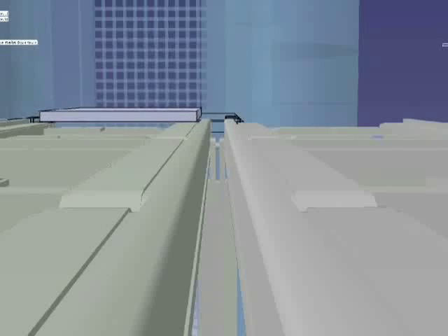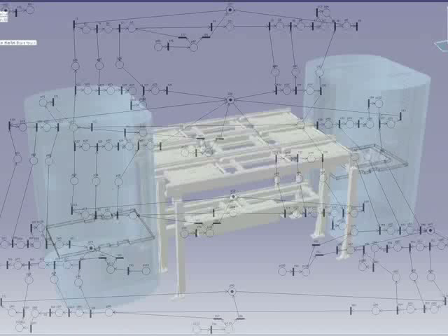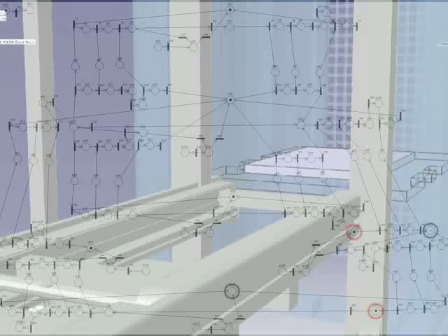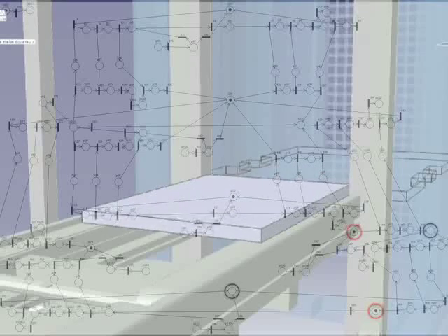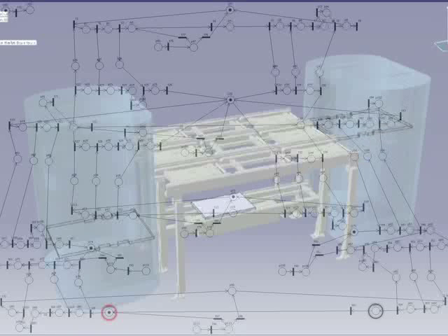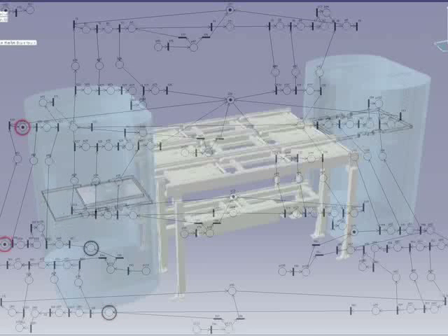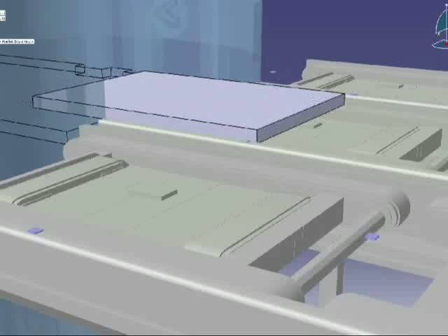Having a flexible system means that the sequences shouldn't be hard-coded, but should be decided on a set of production rules. The orchestrator features a control interface which allows an external participant to take the decisions, for example, routing the pallet when there are many possible paths. The external participants could be anything from a human operator to fully automatic software taking decisions based on business rules. In this case, the role of the decision maker is provided by a human operator using the Materna DPWS Explorer tool as a generic web service client.